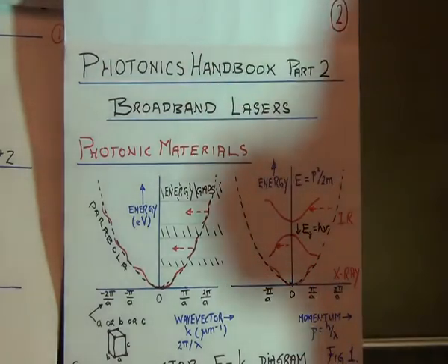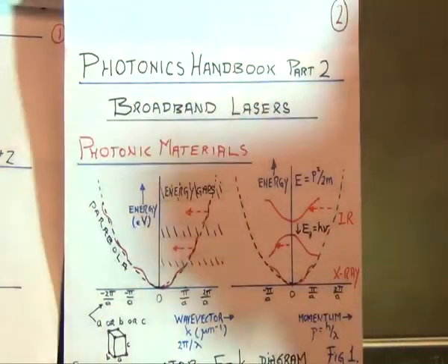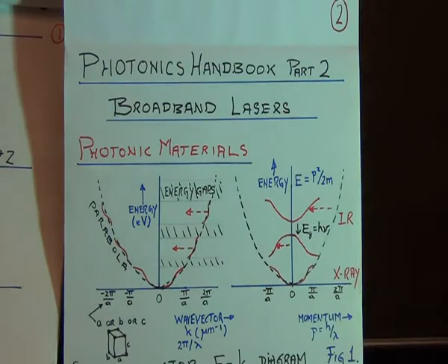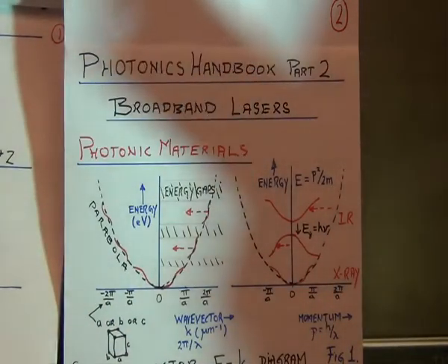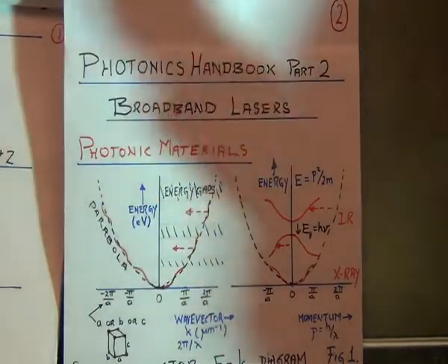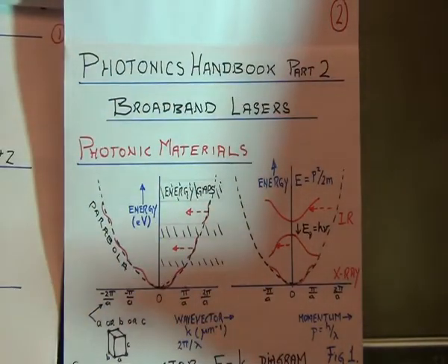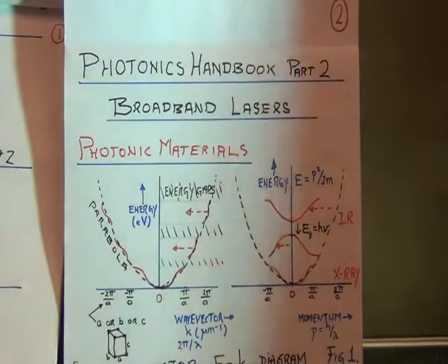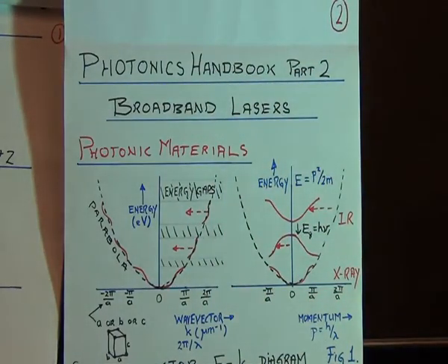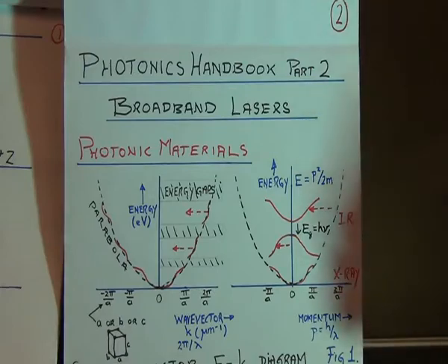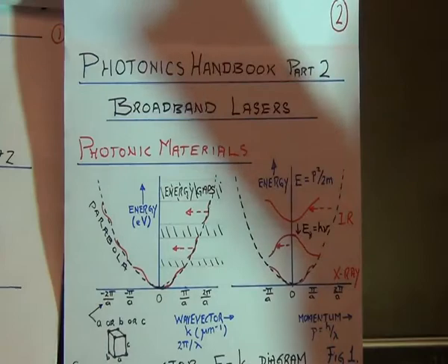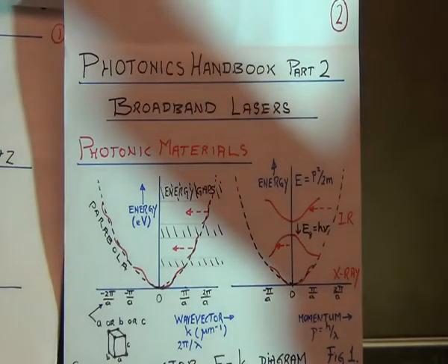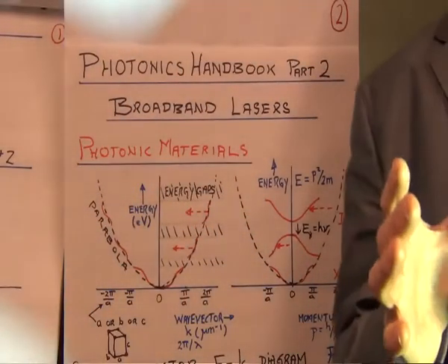However, unfortunately for the silicon manufacturers, the likelihood of a third particle being in exactly the right place at exactly the right time is extremely low. So very, very few photons are emitted from a silicon diode. Now, you can take a silicon diode and strip off the plastic cover and put a very sensitive light detector up to it, like a photomultiplier tube.